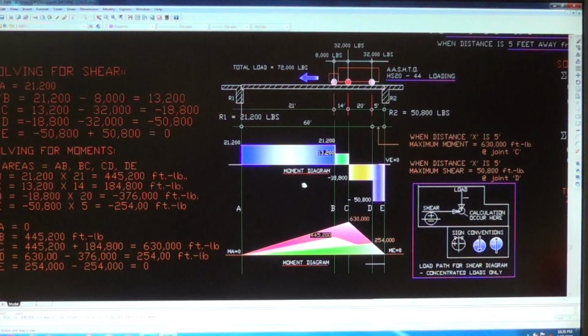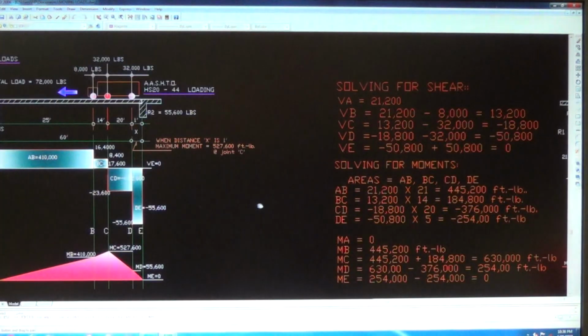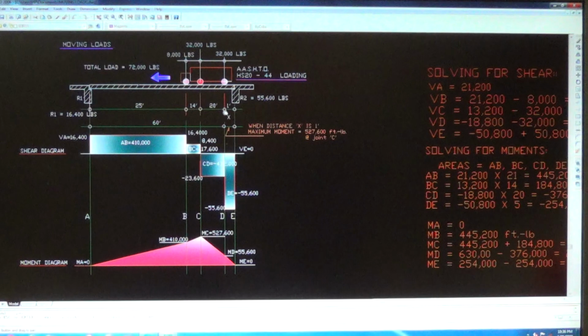As I mentioned before, the location of the most critical shear of any horizontal member subjected to loads is a very close distance from the face of the support. Okay, you can't get any larger than that. That's the approximate location. That's why in the first video I started at a very small pace to see the most critical shear. This is the largest shear.